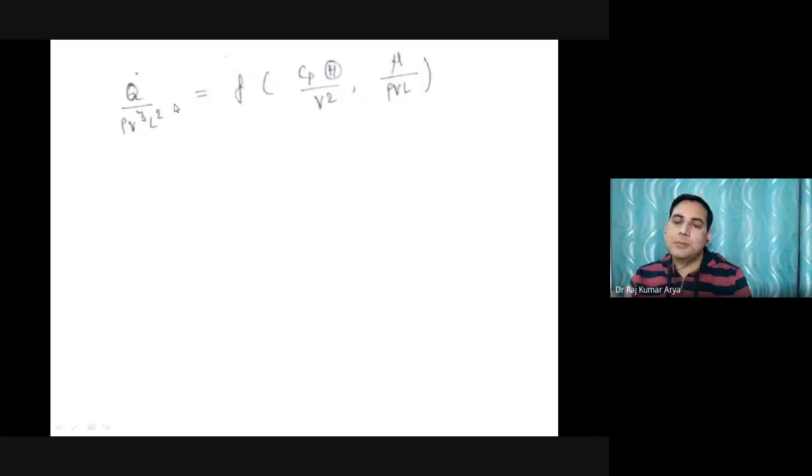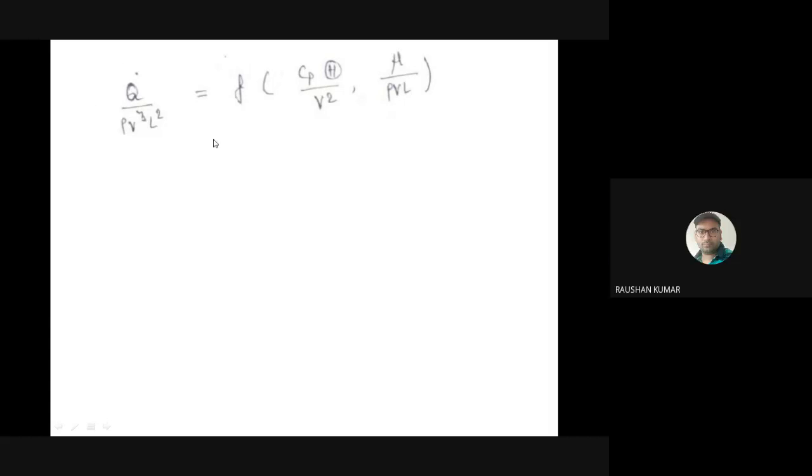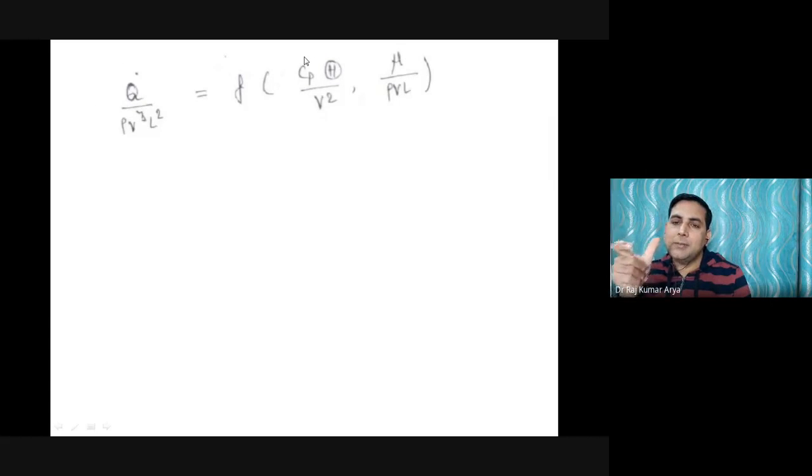So now you can put your function, because your Q was your dependent variable, and the rest are independent variables. This was your pi group 1, and now you got three pi groups only, three dimensionless groups: group 2, group 3. So your Q by this is a function of those. Based on that, you develop your correlations. How those would be correlated will come from performing further practical experiments. You will have some functions, some correlations of that.